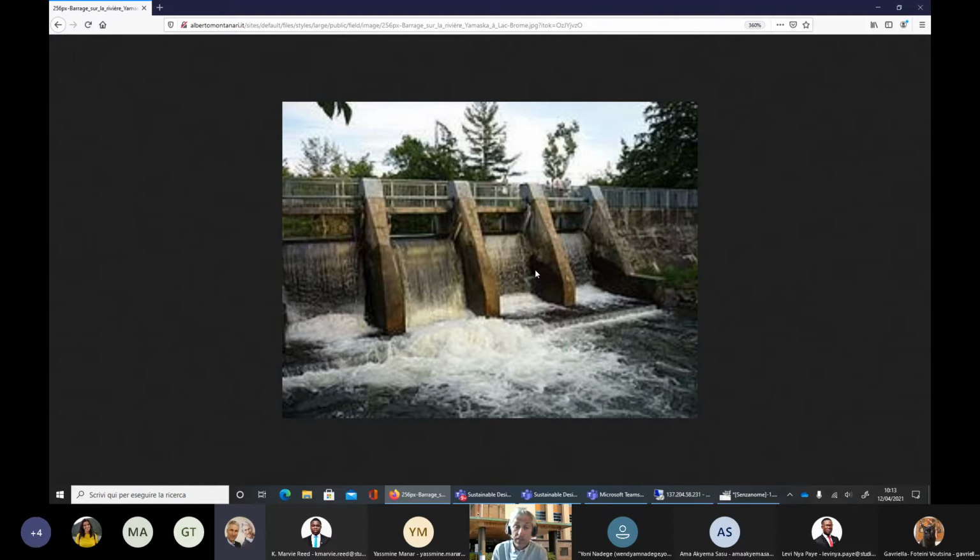For instance, upstream, we have to get water from the river. And if you want to get water from the river, you need a high water level, because water flows down by gravity. And where you get the water, you have to have a fairly stable water level. You don't want the water level of the river to change a lot from one season to another, because if you put there a pump, or a pipe to get the water, you need some stability.